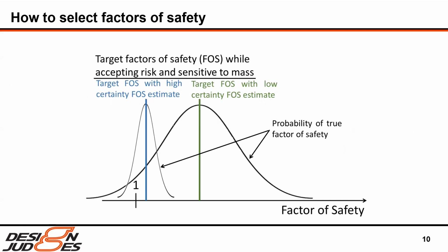But one thing you should keep in mind is you should not just move on to the next step in the design process when you find the minimum factor of safety of your design is above your target, or especially if it's below it, right? You don't want that. So if it's above it, you should always attempt to lower your factor of safety to your target, and to have that factor of safety throughout your part if you want your design to be as light as possible. You can perform topology optimization, but you can also find where there's little stress in your part and remove the material in those locations, and then add material to hold the loads where you believe you can hold them in tension and compression and shear through looking at the load paths, and then reanalyze your design and iterate.